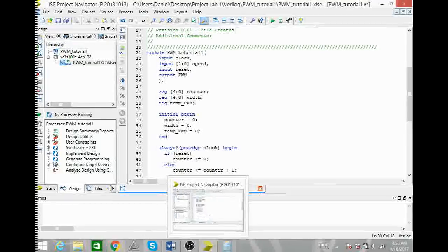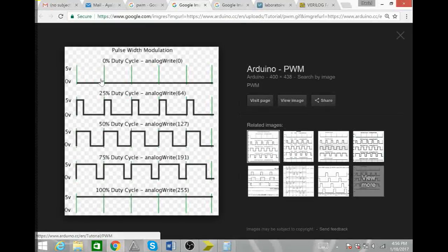So with that in mind, we can think of this counter going from 0 to 31, and then at 31 all 5 bits are 1s, 11111, and then after you increment by 1, it resets itself to 0 and continues incrementing back up to 31, and then resets itself back to 0, back up to 31, resets itself to 0, and continues to create this set period.